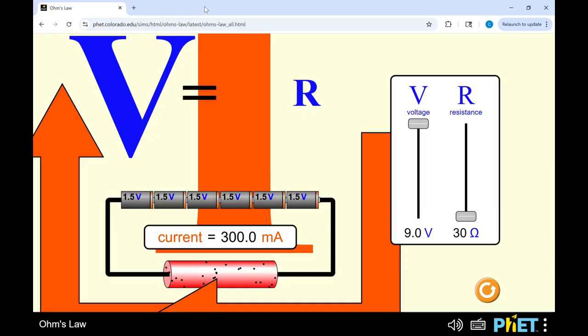Its units are ohms. The difference between an object's resistance and resistivity is that resistance depends on the object's geometry, such as its size and shape. Resistivity is an intrinsic property of the material, where each object opposes the flow of current regardless of its size and shape. For example, all copper materials have the same resistivity, but its resistance can be affected by changing the copper's geometry.